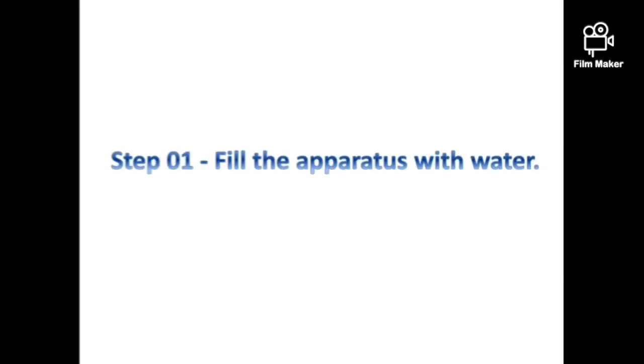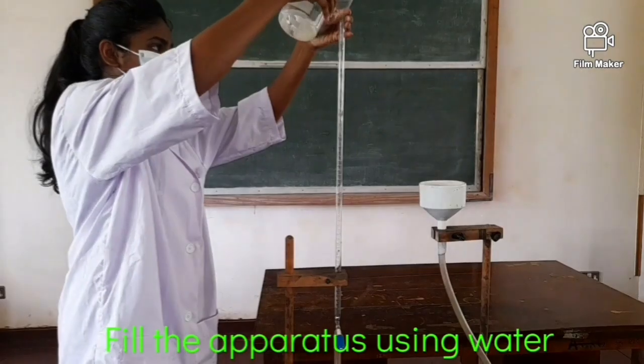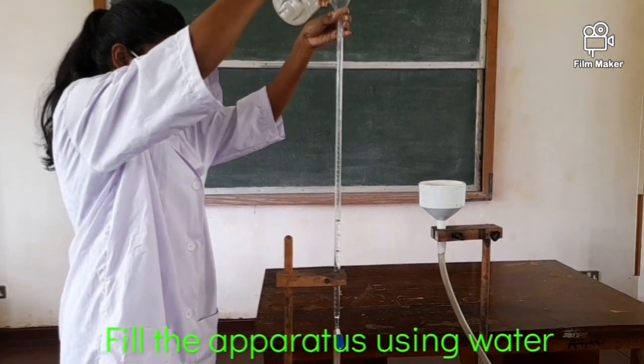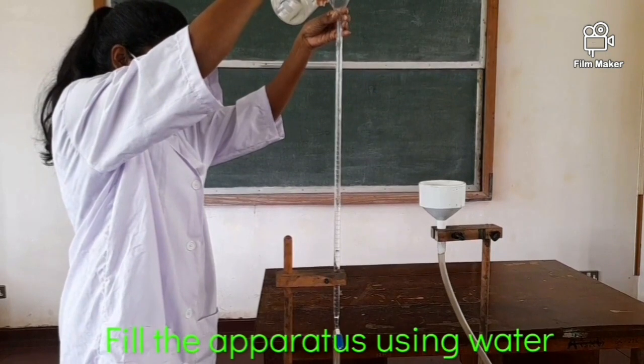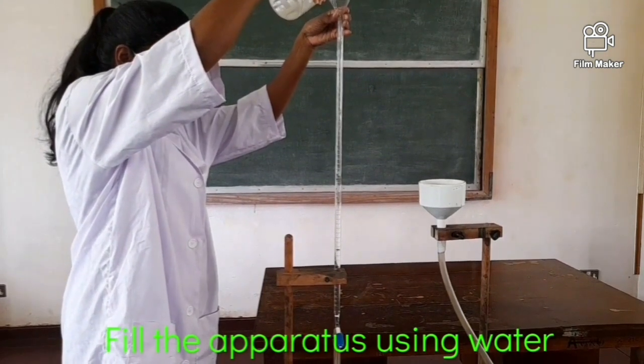Step 1. Fill the apparatus with water. This is the model apparatus of the practical. At first, you have to fill water from the burette side of the apparatus until the apparatus becomes steady, with no air bubbles trapped within the system.